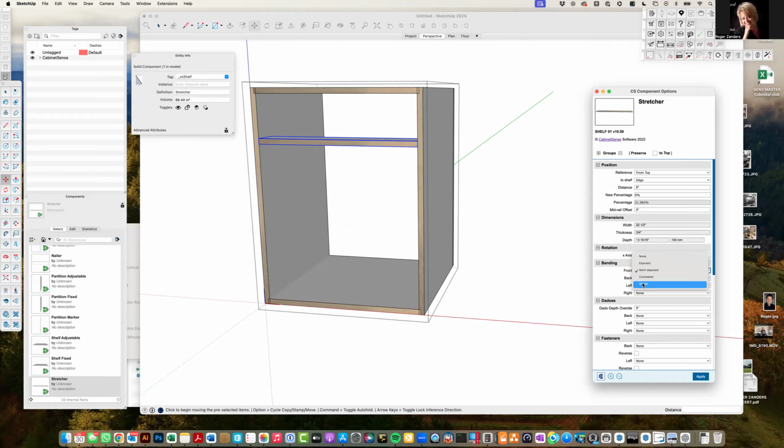So if we wanted white melamine edge banding on the shelves, but we want something else on the cabinet that matches the carcass, the white oak or the walnut or the mahogany or whatever else, that makes total sense. Scribe adds length to a part invisibly until we export it, and then it gives us that extra length of our scribe dimension. So that's why we need more than these here, and they're being added, if I'm not mistaken. So semi-exposed is what we'll put for that.